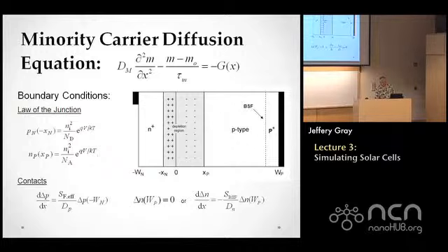So this emitter region right here is a source of the series resistance. Let me get back to that. Everyone here, I'm sure, has had differential equations. You need a region in which you're going to solve that differential equation, and you need two boundary conditions. Here we actually have three different regions. We can only apply the minority carrier diffusion equation to two of them, the so-called quasi-neutral regions.